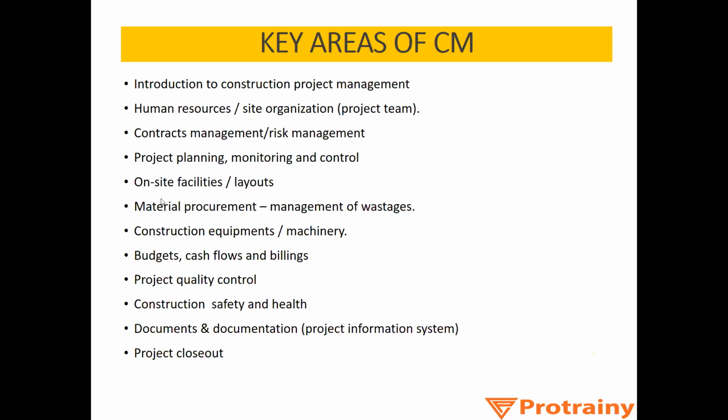Then you need to see all the on-site facilities and layouts. What are on-site facilities? The labor colony, the place where the labor will stay, where the security cabin will be, how you are going to barricade the project to stop theft from site, how many security guards you need to put and where they will be placed, when and from where the truck will enter, and how the truck will move throughout the site. All these things come under on-site facilities and layout, which an effective construction manager and project manager need to understand and manage in their own project.